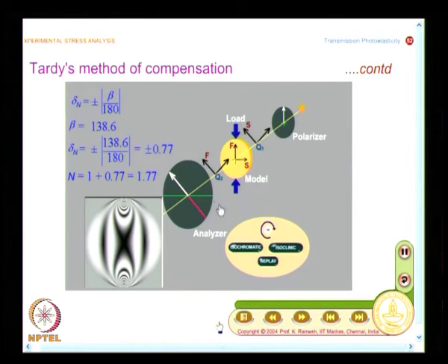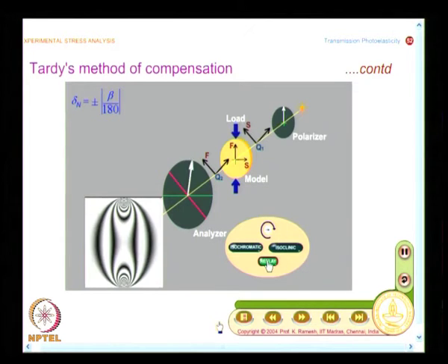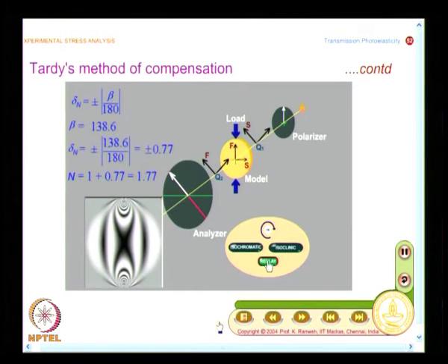I find that I have to rotate by a longer angle, number 1, and I will replay and then ensure which fringe order has moved and occupied the position. So, which fringe order has moved? Fringe order 1. In the earlier case, we saw fringe order 2 came and occupied the position. In the second case, fringe order 1 has moved and occupied.